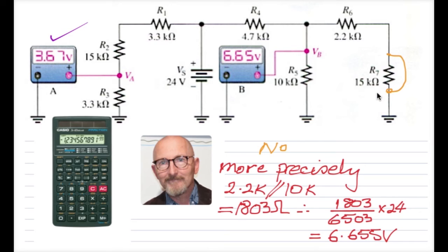We have a short circuit. Resistors themselves don't generally go short circuit, they generally go open circuit. So more often than not, it would be a short circuit on the printed wiring board or something in the wiring which has caused the short across that component. So troubleshooting 101, we've killed it.